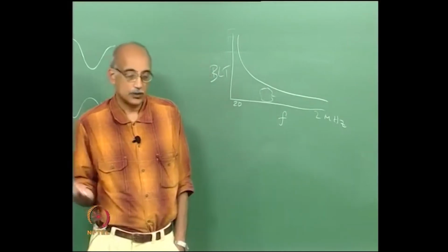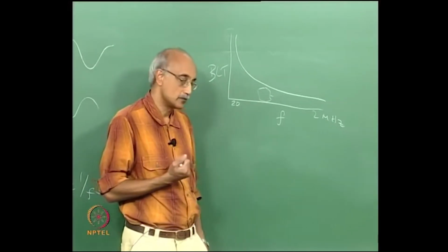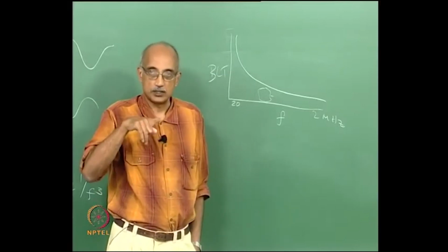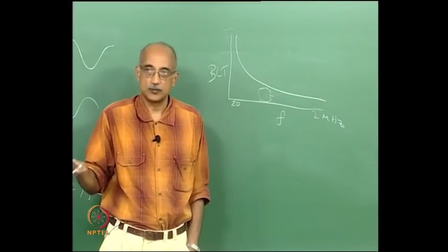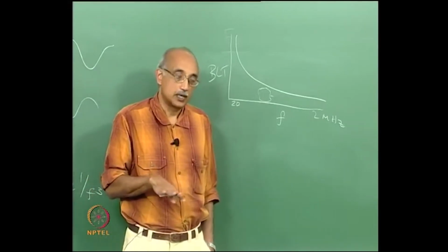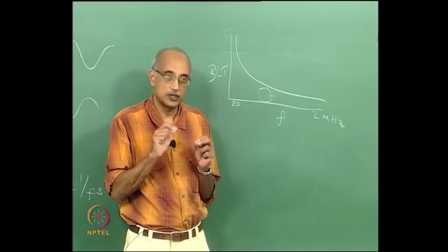The third reason for doing high frequency particle removal is that as you keep increasing the frequency, what happens? The cycle is very fast. So, bubbles form to very, very fine sizes and then they collapse immediately, and that is why cavitation forces are very low. But the other implication of that is the density of bubbles is much greater.